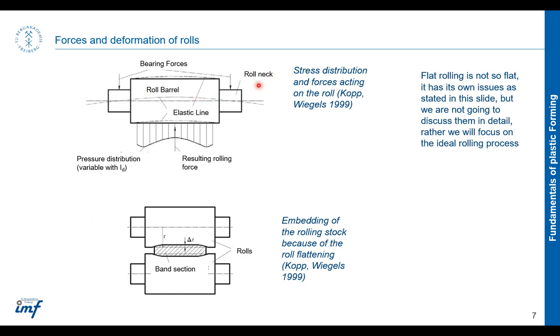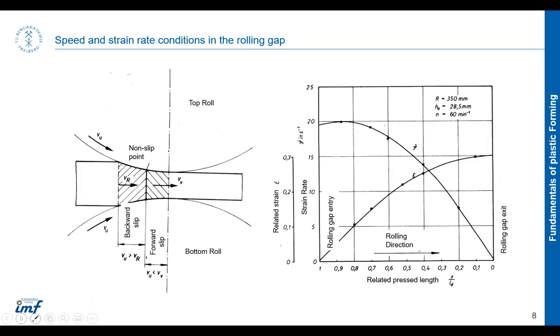bending, we have fixed roller from these ends, but it is exerting a consistent force here on the sheet. So we have buckling in the roller, which we can see here, and this disrupts the overall profile of the sheet which is being rolled, and therefore we get this kind of phenomena which we have to control by adjusting the forces and overall effects. So we are not going to analyze this, but this also comes into effect.